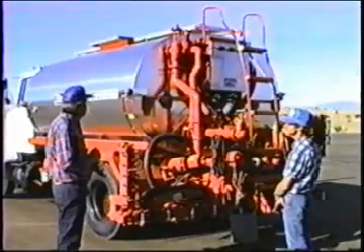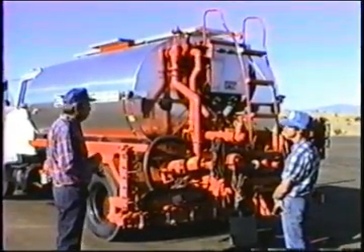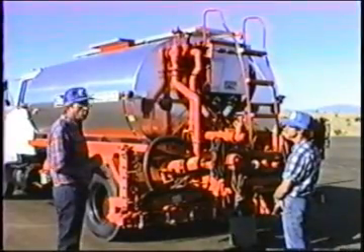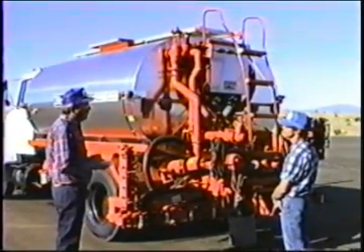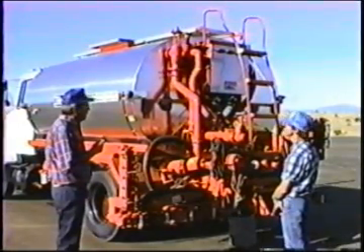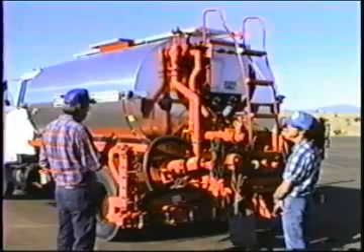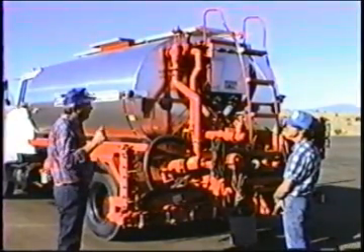If we get to the job with a tank full of hot asphalt and a wet spray bar, then we want to set it up and be sure that the first bit that we spray goes out the spray bar and nothing circulates into the tank. And the way we would do that would be to open the spray bar valve, open all the valves in the spray bar.